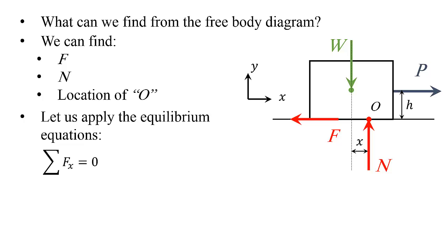If I do the summation of the forces in the x, I will find that F equals P. So now I just solve for F. If I take the summation of the forces in the y, I can get the normal force, which will equal W.